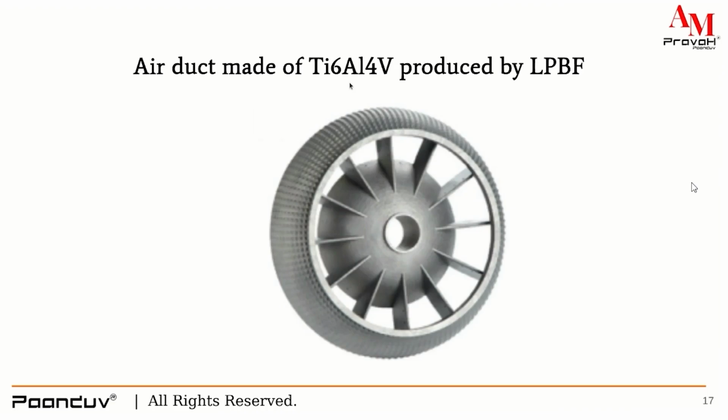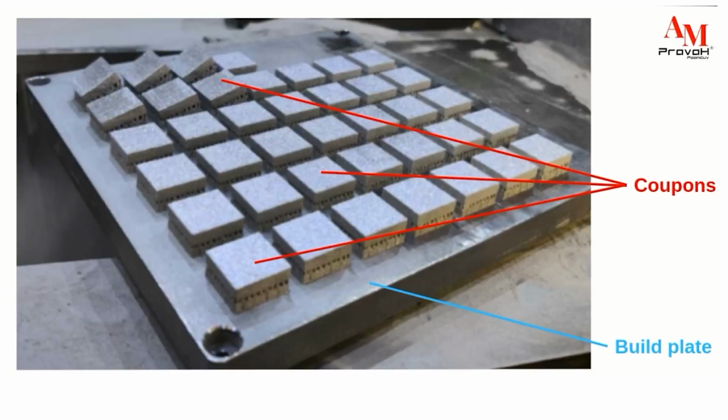Now, what is the strategy people generally follow? They have the alloy in their hands. They may or may not have a starting point for the process parameter window to get a high quality build, and hence they will explore or optimize the process parameters by creating coupons. They will cut these coupons, characterize them, and understand the porosity and the defects being created in these coupons. Once they get high quality coupons, they will proceed further to part manufacturing.